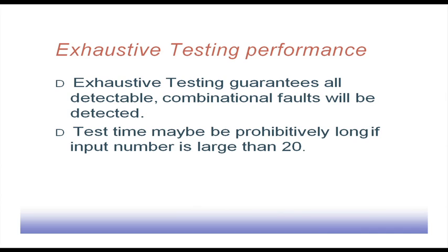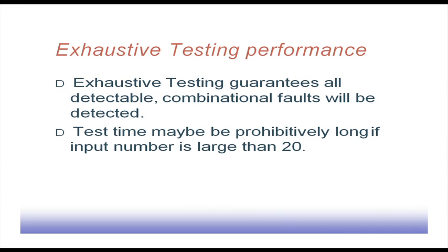Now, this LFSR or the CLFSR and these counters can be used for generating exhaustive test patterns, because all the patterns are generated by these structures. The problem is that exhaustive testing is good, because it guarantees all detectable combinational faults are detected, but at the same time test time becomes prohibitively large. If the number of inputs is more than 20, then you require a large amount of time to generate those test patterns and apply them to the circuit.